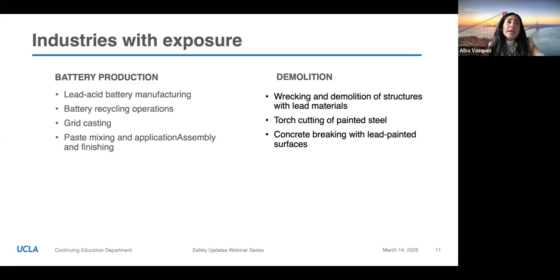And mind you, that's why during the cleanup, there were 2 stages with the wildfire cleanup. It was supposed to be where homeowners wouldn't go back to it unless it was rendered a safe site. Nevertheless, if you're called, let's say, to build or work there, you really need to know whether or not, because this is safe for the homeowners, but what about if you are going to start doing construction activities or digging a trench, for example, in those sites? You need to know the lead content for the soil that you're going to be working with. So it has to be tested.